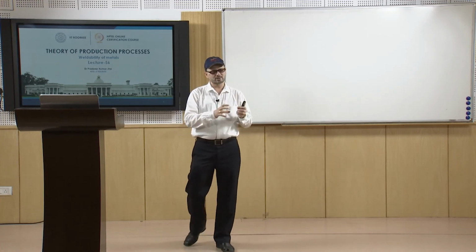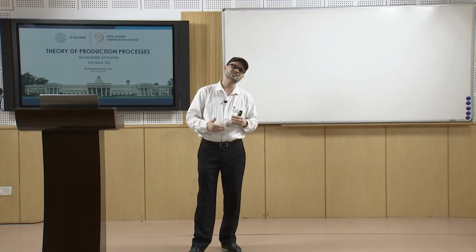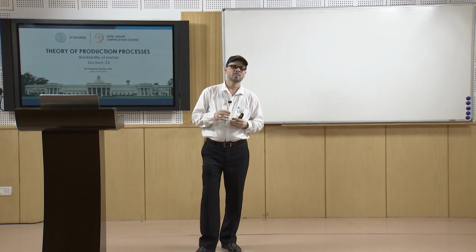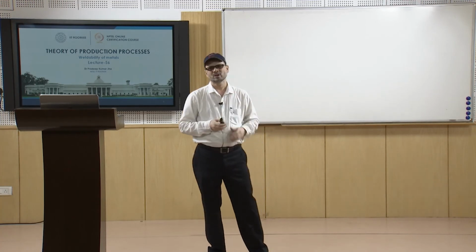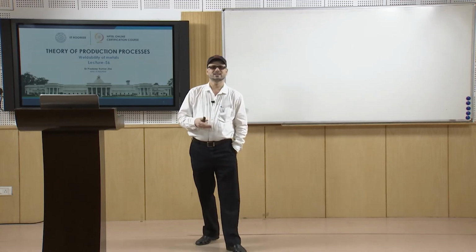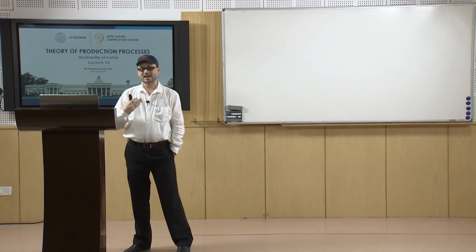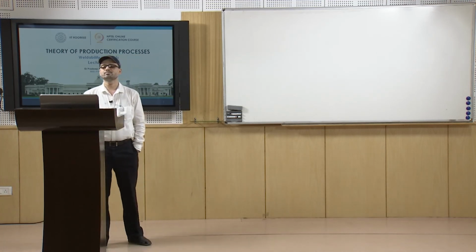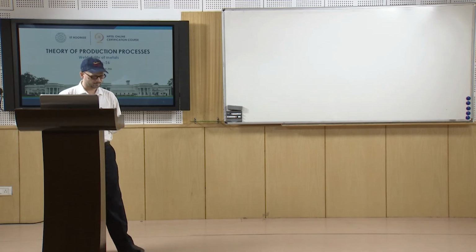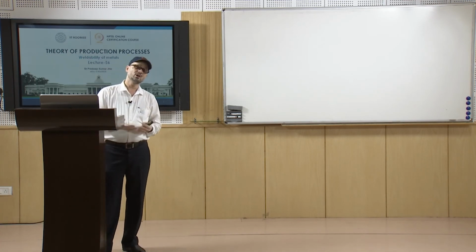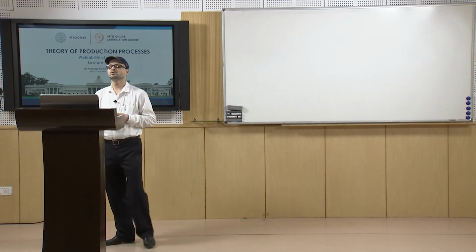Now, if you change the preheat, different values of preheat, and then you judge the quality of the weld pool, the strength of the weld pool. So, that will help you in assuring that yes, the property will be better at which degree of preheat. So, it will also help you to decide about the degree of preheat. Then you also have the information about the energy input. What should be the proper energy input which will give you the sound weld in those cases.